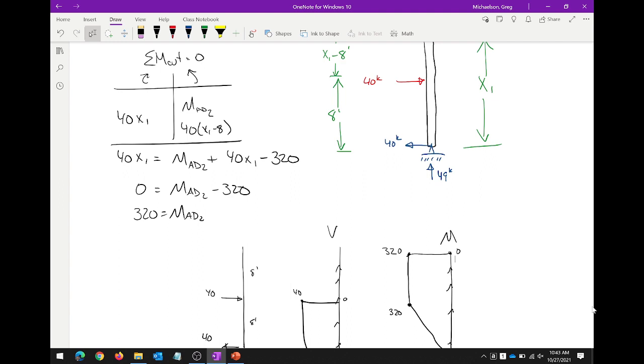For the use of symmetry on any of these kinds of problems, it just has to be the same loading on each side, from the midpoint. Then you can use symmetry. Admittedly, symmetry is a tough one to use for problems like this. You have to have symmetry with respect to the geometry, like a simply supported beam. You have to have symmetry with respect to the loads, and with respect to the stiffness, right? You also have to have symmetry with respect to the point of interest.